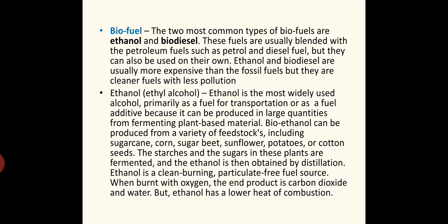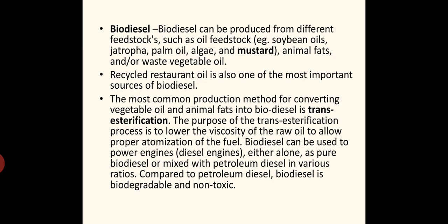See, for producing ethanol the process that we have used is fermentation, but for producing biodiesel the process that we use is called trans-esterification. The purpose of the trans-esterification process is to lower the viscosity of the raw oil and allow the proper atomization of the fuel. Anything which can be used as a fuel must have the correct viscosity as compared to petrol and diesel. Then only we can atomize the liquid by providing it into the engine cylinders.